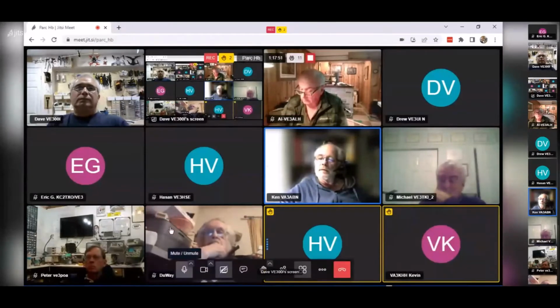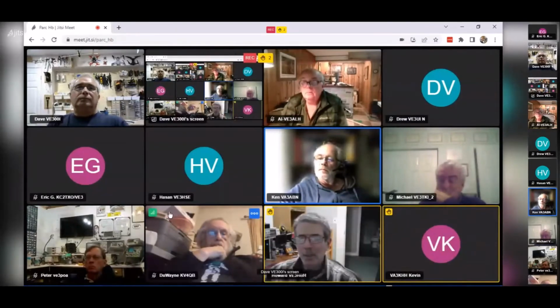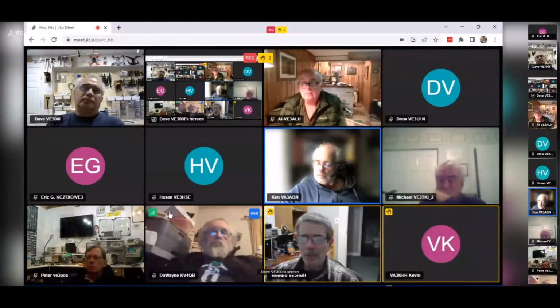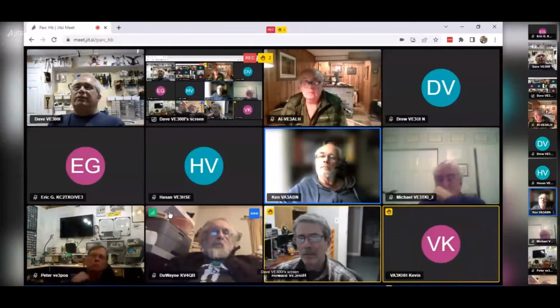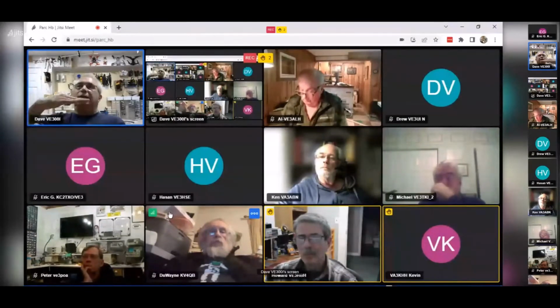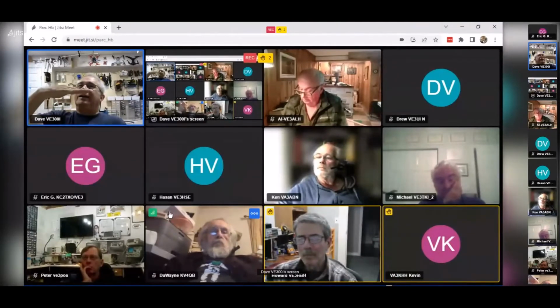Really interesting project, Dave. And since it's rate based, when it starts up, how does it know where it is if it hasn't moved? Good question. That's why you have to use the accelerometer. You always seed an accelerometer value. You start off with an accelerometer value, you seed that, and you hope it's right, because if it's accelerating, you're going to get a wrong answer. You're going to get a bad initial condition.